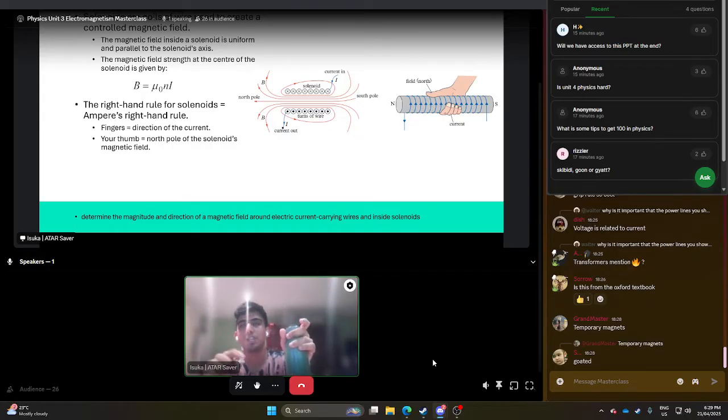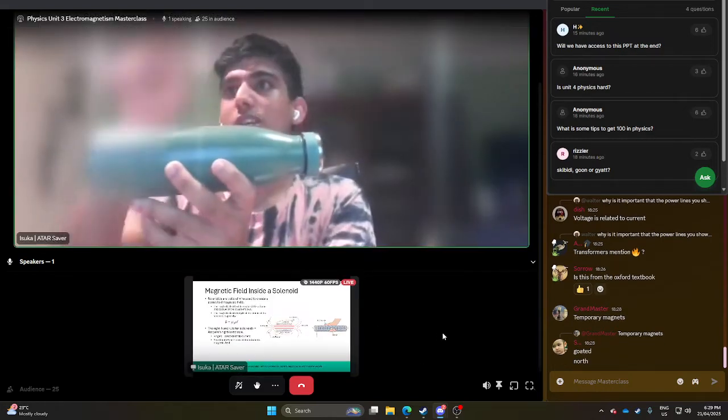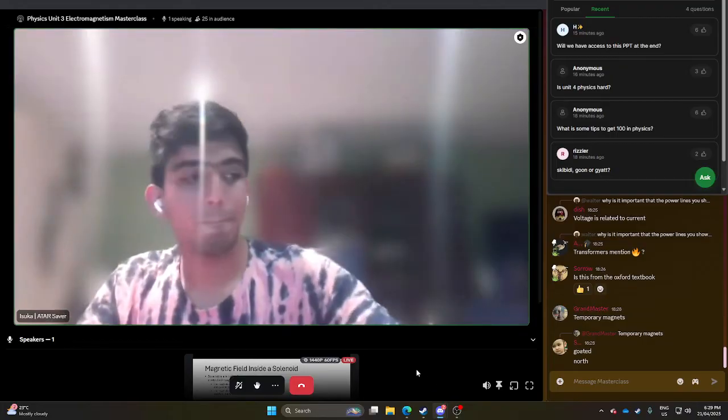A lot of people get confused here, and I'm sure you guys are not, but I'll mention it anyway. They're asking, where do we take the direction of the current, right? The direction of the current is taken from one direction. So if it's this direction, take it from this direction. Just be consistent with it, right? So if it's going down here, your fingers should be going down like that. And then because of that, where's your thumb pointing now? It's pointing that way. So that's where your North Pole is. It basically directs your North Pole, right?